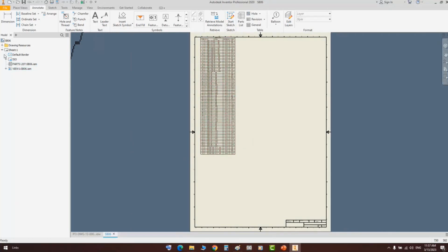To define a border, you need to make it as we discussed. All of those things which we discussed, like making a parametric or custom parameters or all of that, you will not be able to import from AutoCAD. So it's one time, you can make it one time in Autodesk Inventor and use it after that. Let's say it will take a day from you, okay, but you will use it all the time after that. So it's better to make it. You can import it from AutoCAD, but you will lose a lot of things.